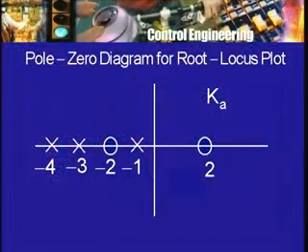So, I am just going to show here 1 zero at -2 and 1 zero at +2, and I want to look at it as Ka varies and not with Ka equal to 100 only. So, I will just write Ka there. So, this is the problem, represented on a pole-zero diagram. The zeros are given, the poles are given. The gain Ka that sort of sits between the two is to be varied, what happens to the roots of the characteristic equation or the characteristic polynomial?